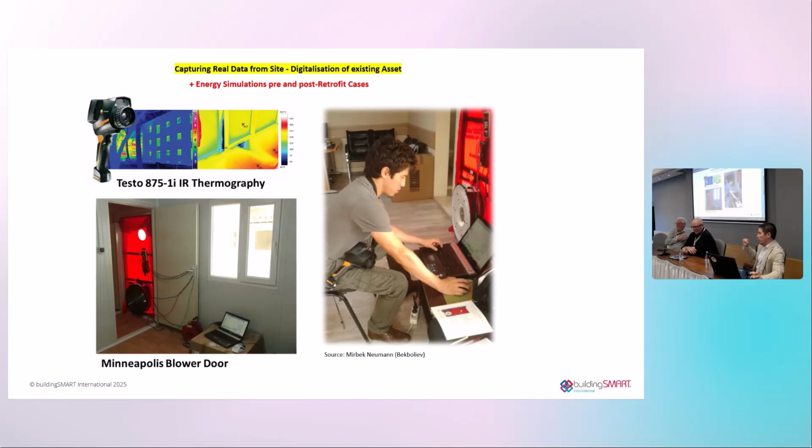You blow air inside by creating a positive pressure, 50 Pascal, or you create a negative pressure, minus 50 Pascal. By doing so, you close all windows and designed openings, they should all be closed, and the undesigned openings like cracks, some problems will be directly visible with your thermal camera. As an example, you can see on the door and windows there are some gasket problems, which is what we had exactly in your case.